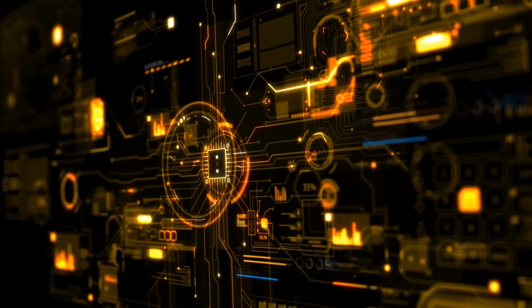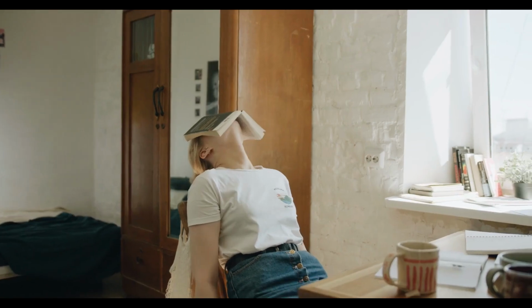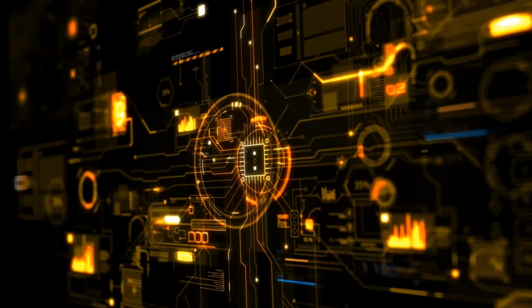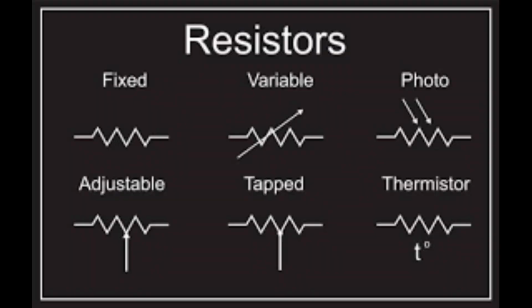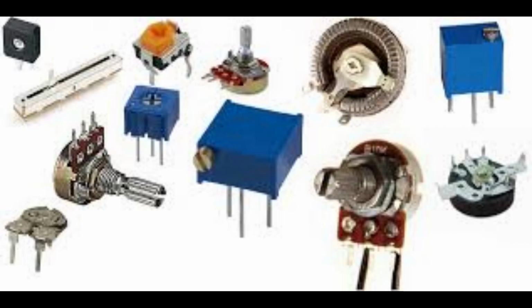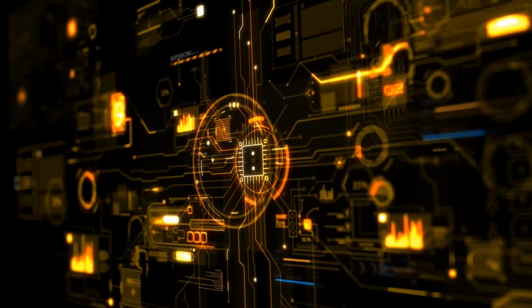Resistors are measured in ohms, and 1 ohm can be quantified as 1 volt of potential energy pushing 1 ampere of current through a circuit. Don't worry about all that mumbo-jumbo for now, but it's important to identify resistors in circuit diagrams, PCB boards, and service manuals. Resistors are typically symbolized as a zigzag or square-shaped sign with its value denoted on top of the symbol. If you may not know, resistors come in either through-hole technology or surface mount package types, and as static non-changing or special variable resistors. Static non-changing resistors can be identified by a standardized color code.